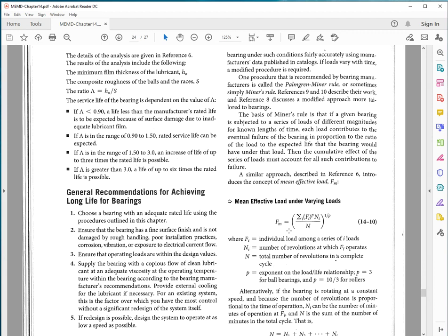Okay, so I have first gear, I know the torque transmitted, I know at what RPM, so I can calculate the first load, and then say it's a 5-speed manual transmission, I can calculate the others. There are more factors, so you don't need to limit it to just the speed, but also the instances of operation. It could be during acceleration, starting from a stop, or cruising. Anyway, you're assuming that this pattern is repeated for the entire life of the bearing assembly as it's used for its application.